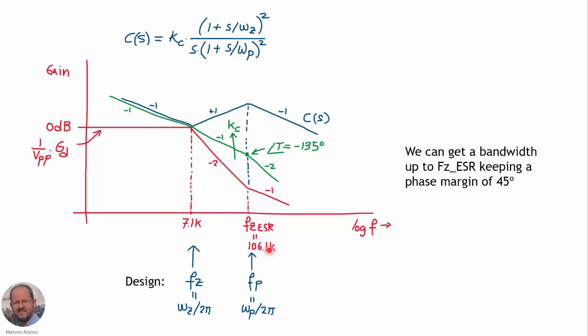We usually need to make our system stable and operating in the linear region, so that the duty cycle changes slowly compared with the switching frequency. So now that we know what we can do, we are going to do the design mathematically and try to find a better design for our converter operating in closed loop.